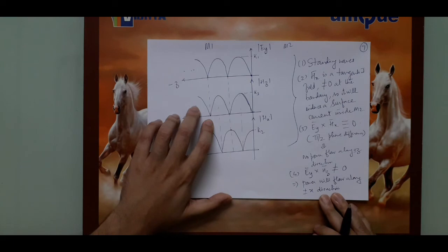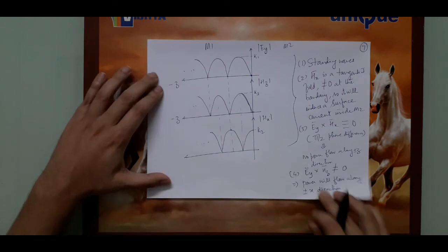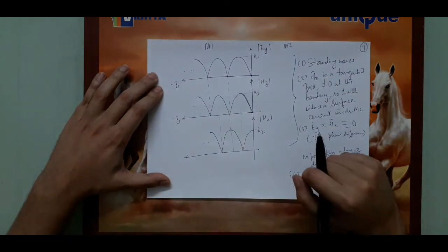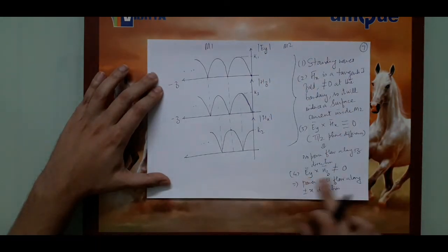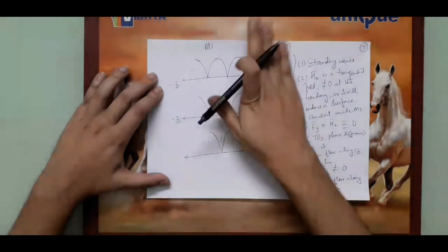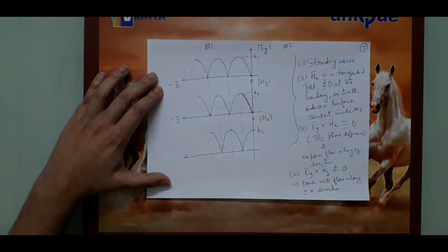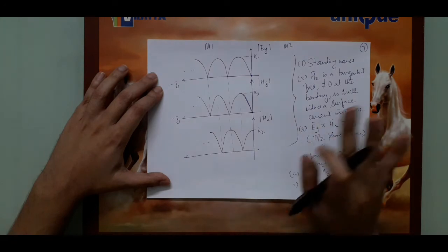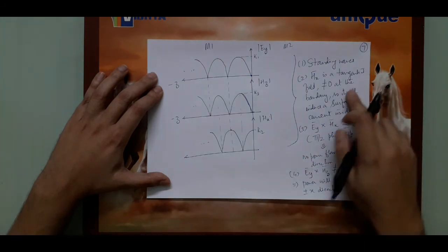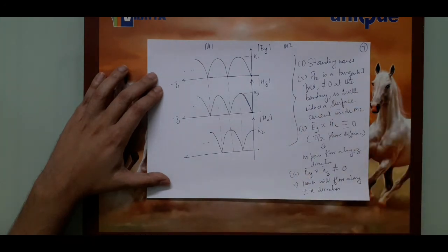So now, since Ey and Hz constitute my power flow, these are the fields on which I will focus. Hx does not constitute power flow. What Hx does is it induces a surface current. That's it.